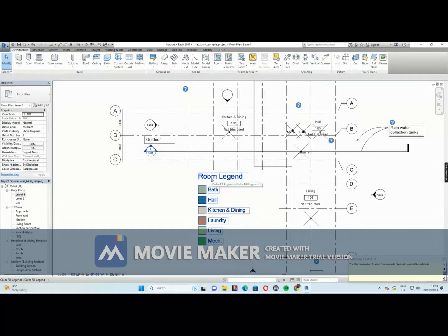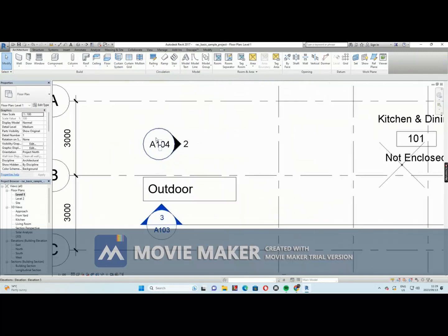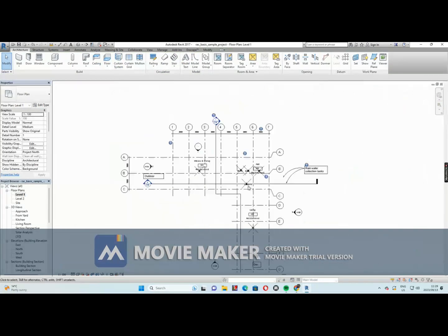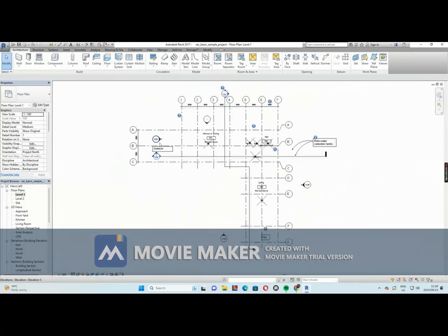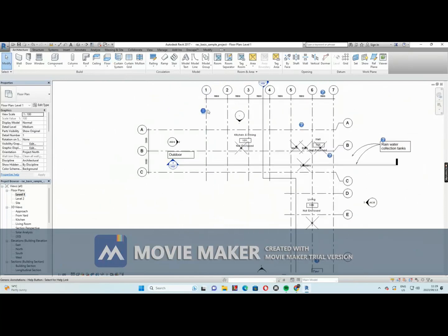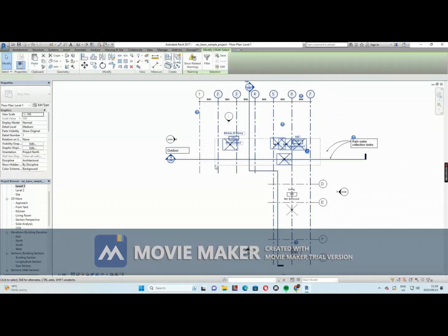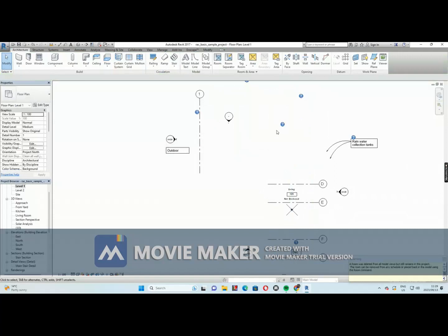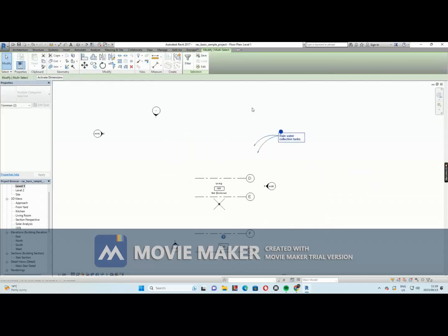These are your elevations. This and this and this, your east, and then this one is your south, west, north. So you don't have to delete this. Once you delete this one, your elevations here, they will go. So you just have to leave them alone. You delete the other stuff, you highlight everything here, you delete. Yeah, right, everything's deleted now.